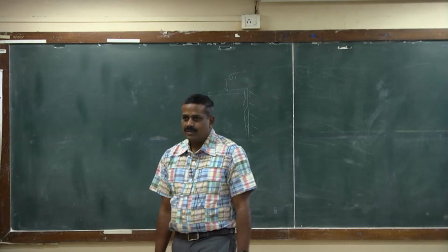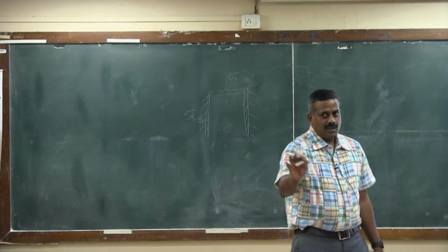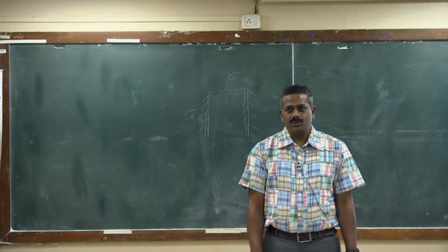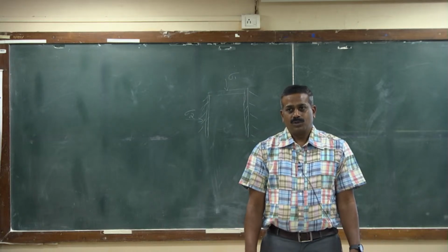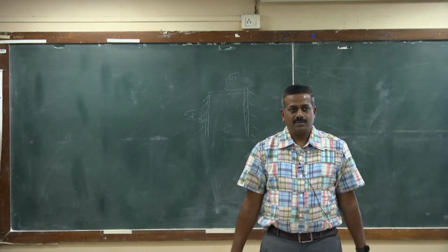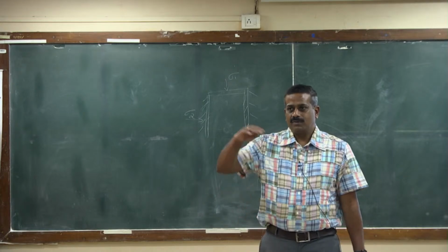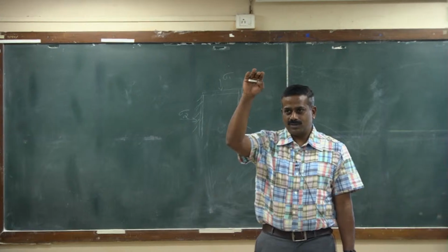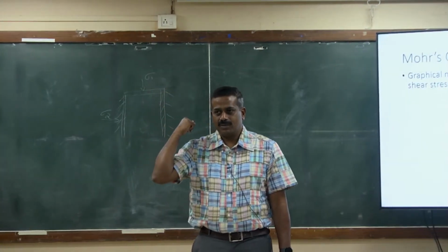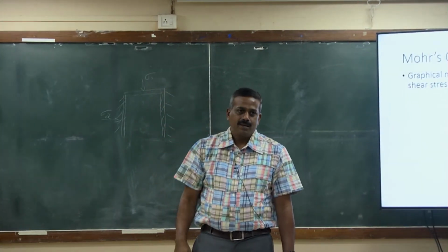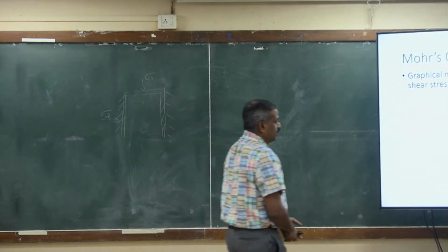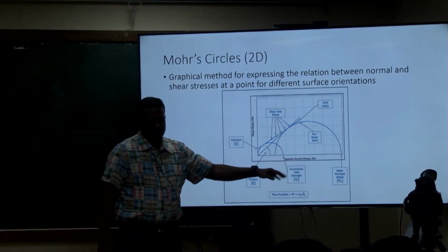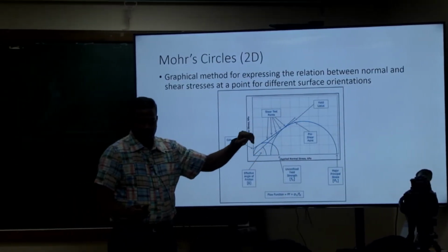In general, we'll talk about the selection of stress too. In general, it's related to your bin size. So if you are storing in like a 10-ton bin, then you'll have to pick some distances within the bin and choose the stress at those heights, and then use that for compaction. Those are the stresses that we will be using here, the applied normal stresses too. Is that clear? But again, we will talk about that in a minute.